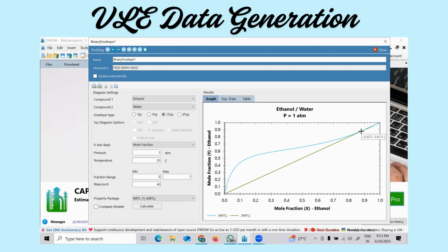But with the literature, once we compare, then you have to judge which model is giving the azeotropic composition nearest to the literature value. That model is our expected model to continue with other operations of the design and other things, right? So this is about generation of the vapor liquid equilibrium data that we have generated at constant pressure, so it is known as isobaric VLE data.